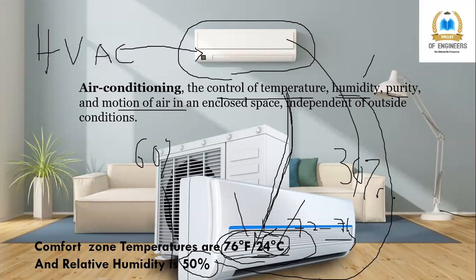Automatically it has equipment, guys. So you don't have to maintain the moisture content. The AC will automatically maintain it. It has the equipment there. It has dehumidifiers. It has humidifiers. So if you have 30%, this machine will add small water droplets. It will moisturize or humidify the air. So one is humidification, another is dehumidification. Two things, two phenomena. So that is how to maintain the humidity.